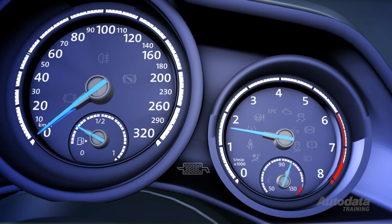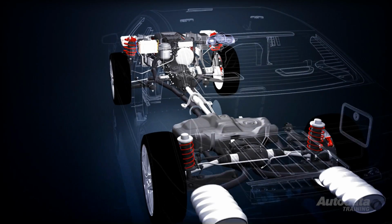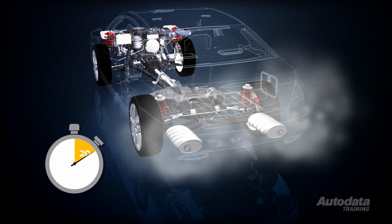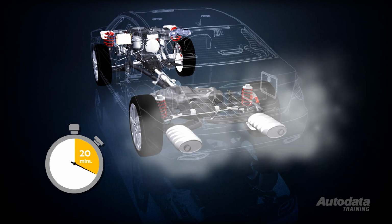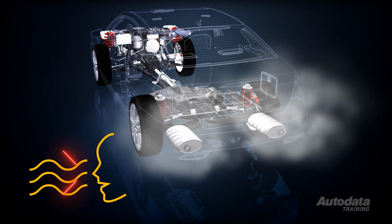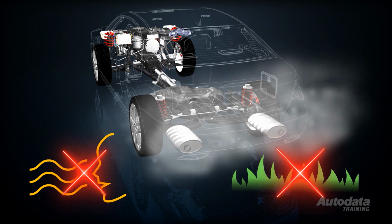Once forced regen is activated, the engine revs will increase automatically. A forced regen will blow lots of smoke and take at least 20 minutes to complete. But beware, a DPF with a high soot loading can take much longer. And remember, don't breathe in the fumes from the regen and don't perform this task in a grassed area.